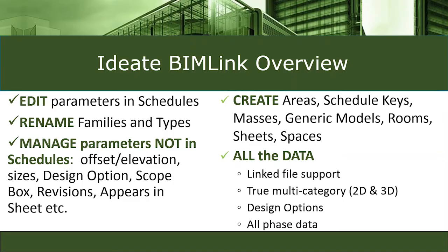So again, an overview of Ideate BIMLink: that first check is what we just saw there. You can actually edit parameters in schedules, so any parameter that you can think of that is schedulable. And then also, if you look at that third bullet item, you can manage parameters that just don't appear in schedules.